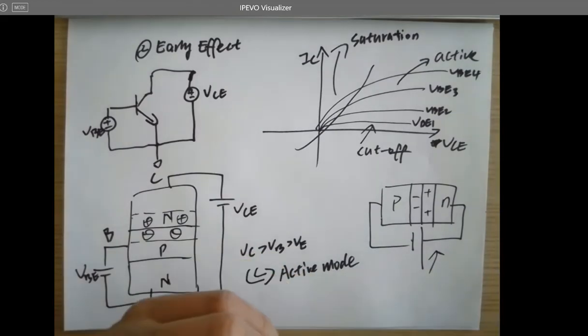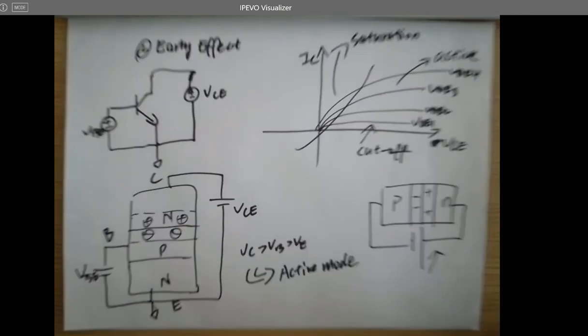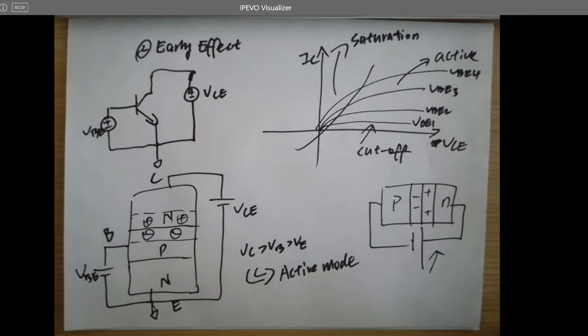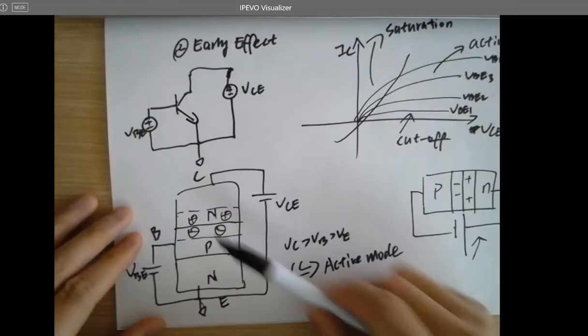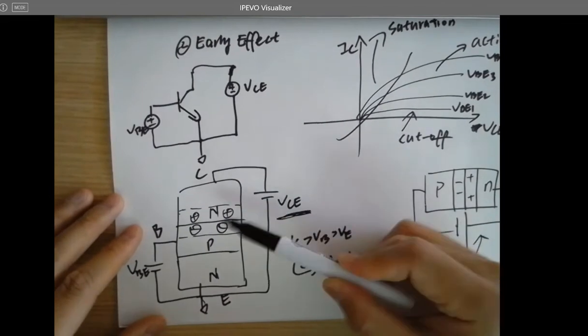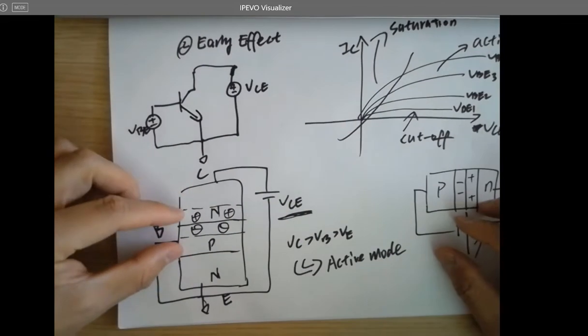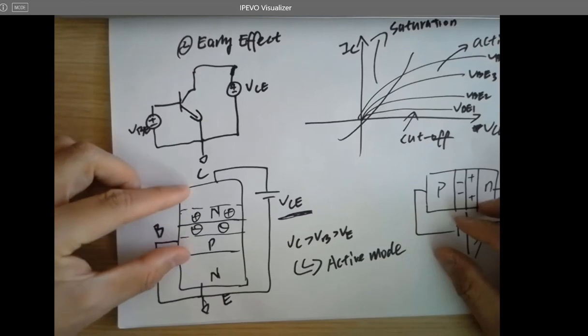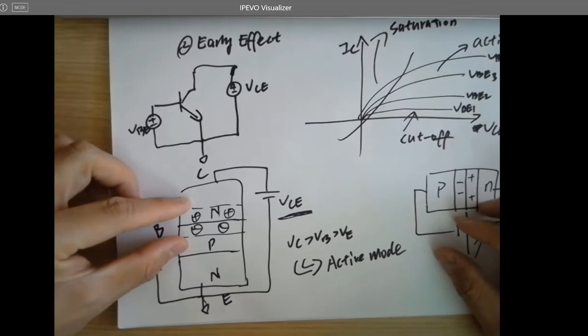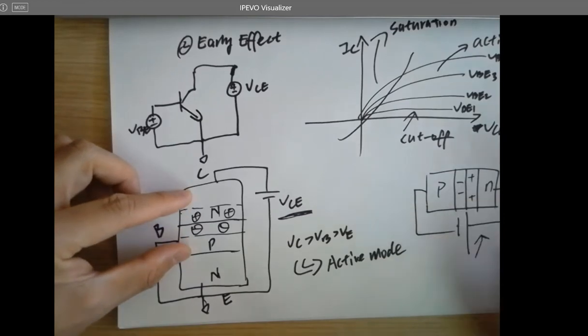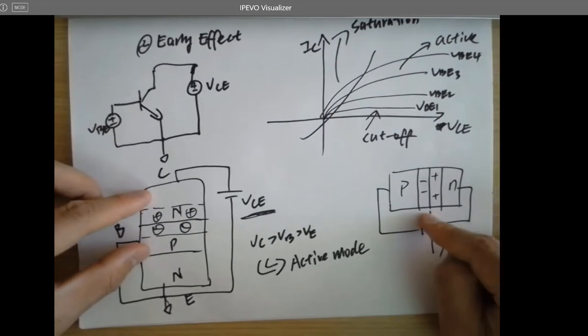So in the opposite way, if you reverse bias it and you increase that reverse voltage, it's going to be wider because it's working against the current flow from P to N. There's only a saturation current flowing through it, a tiny amount of current. So same here, if you increase VCE, will this depletion region get wider or narrower? Wider, right? Same concept. It's getting wider.